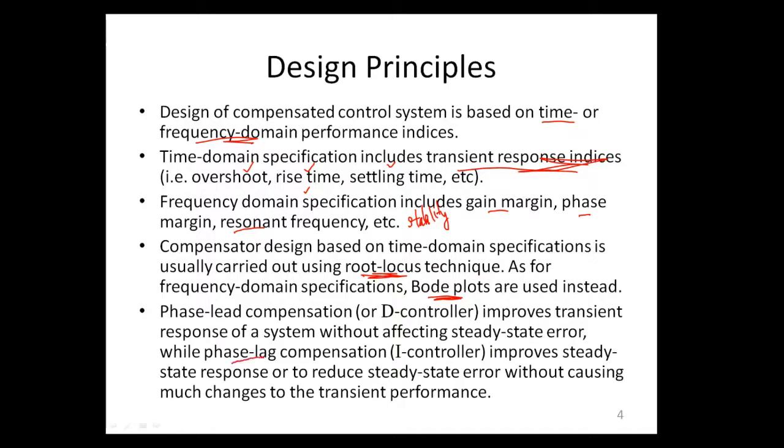Whereas for the phase lag compensation, or the I controller, it improves the steady state response, and at the same time reduces the steady state error, and these do not cause changes to the transient performance. In summary, the main purpose we design a phase lead is to change the transient performance.